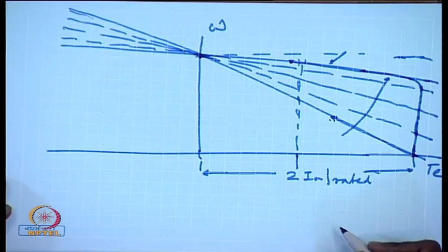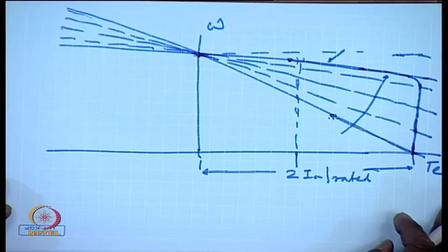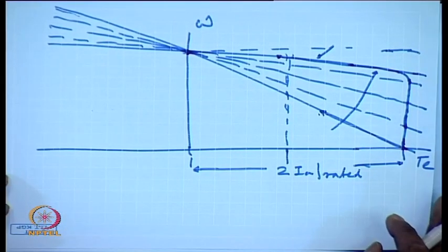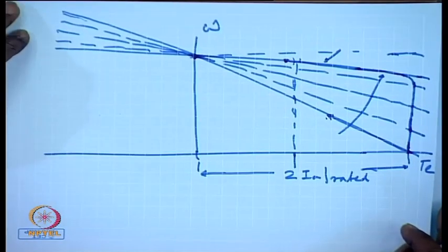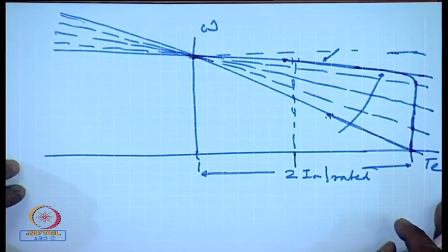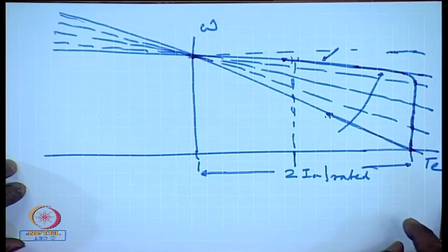This will be the ideal characteristics. However, in practice it is difficult to vary the armature resistance continuously, and therefore, sectionalized step resistance starters are normally used for DC motor starting.